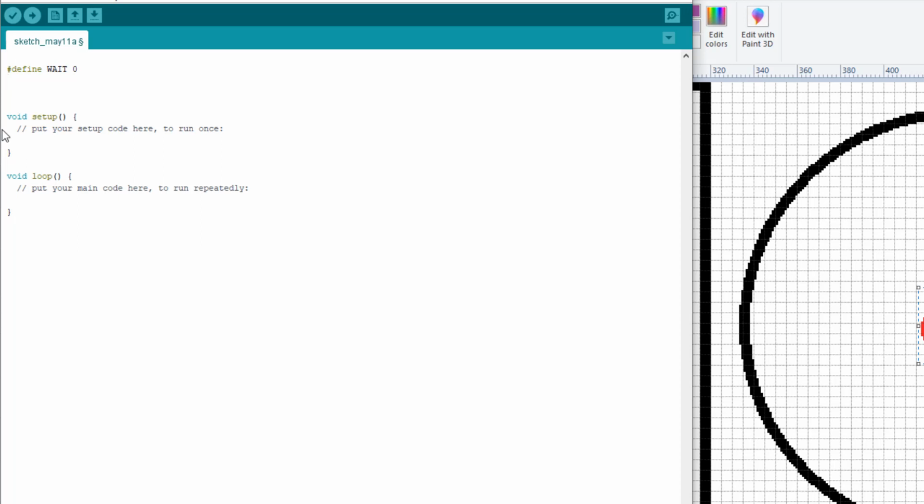And remember when I was talking about memory, using things like #define as opposed to const int, it's going to put that information in a different part of memory. So there are volatile and non-volatile memory. We can store stuff using the #define, or we can store stuff using ints as global variables or constants.